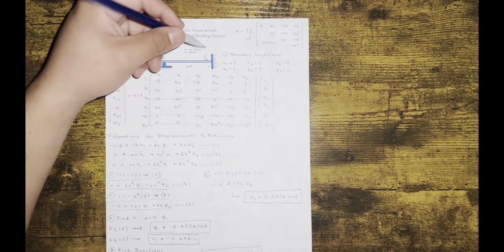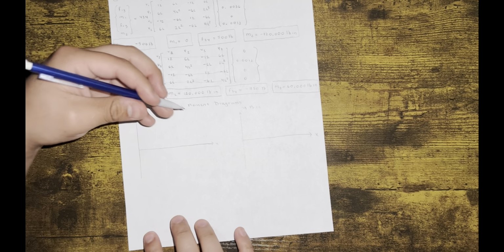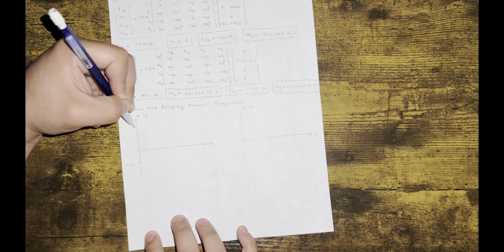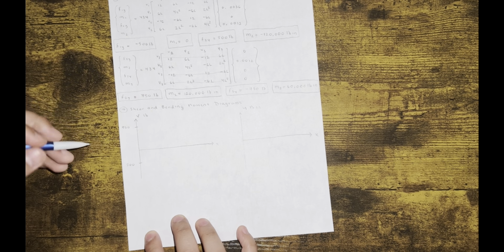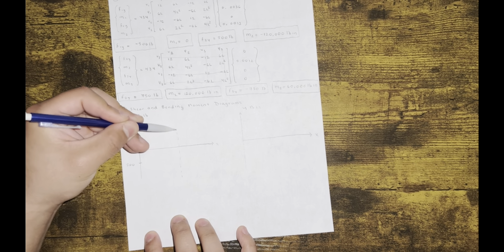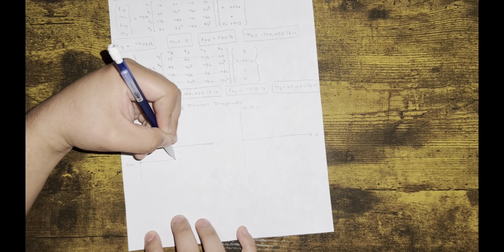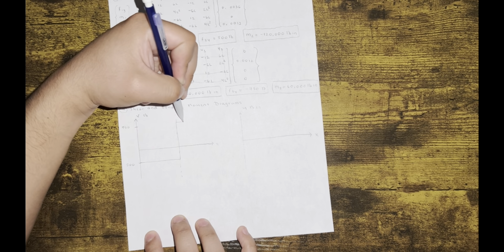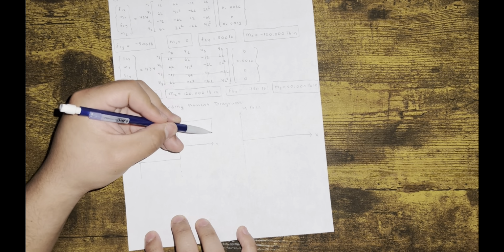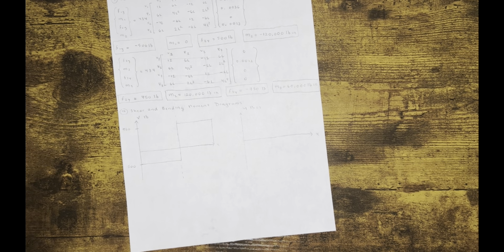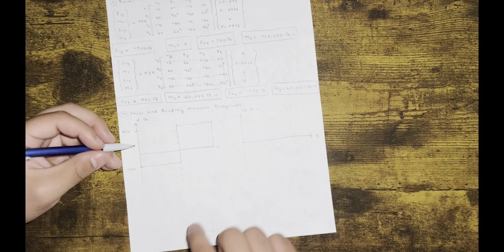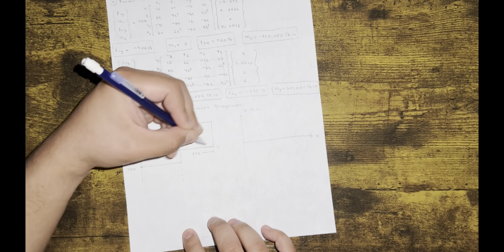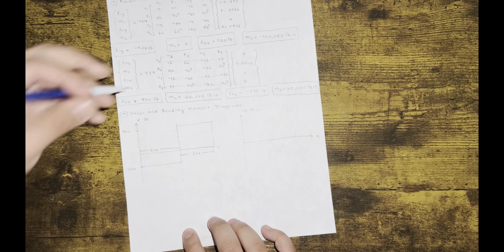So that means that's what our bending diagram is going to look like, right? So let's go ahead and do 500 here. Let's go ahead and do 750 up here. And let's go ahead and assume that's halfway throughout the beam. So we're going to go here. Boom. 1250 pushes up. So we go all the way to positive 750. Nothing happens. And then 750 brings you back all the way down. Okay? And that should work if you did it correctly. You should always end up back at 0. So this was 240 inches. This was 240 inches. And this is how I solve for the bending diagram.